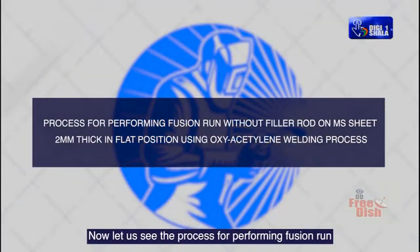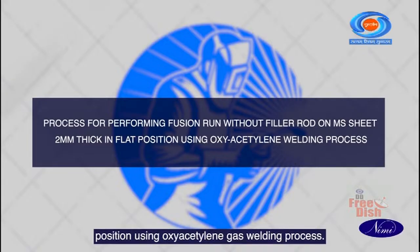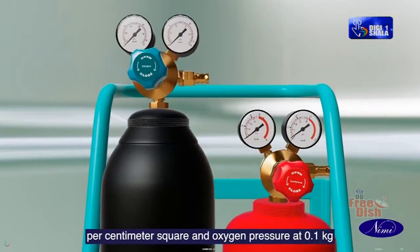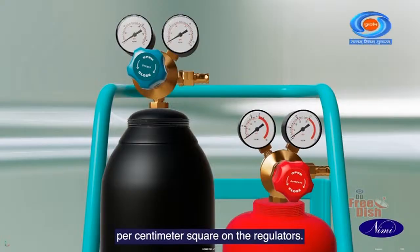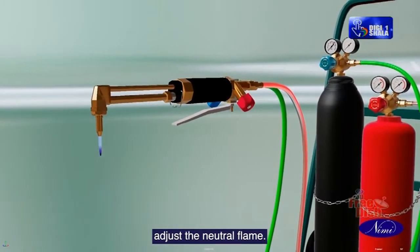Now let us see the process for performing fusion run without filler rod on MS sheet 2 mm thick in flat position using oxyacetylene gas welding process. Set acetylene pressure at 1 kg per centimeter square and oxygen pressure at 0.1 kg per centimeter square on the regulators. Ignite the oxyacetylene gases and adjust the neutral flame.